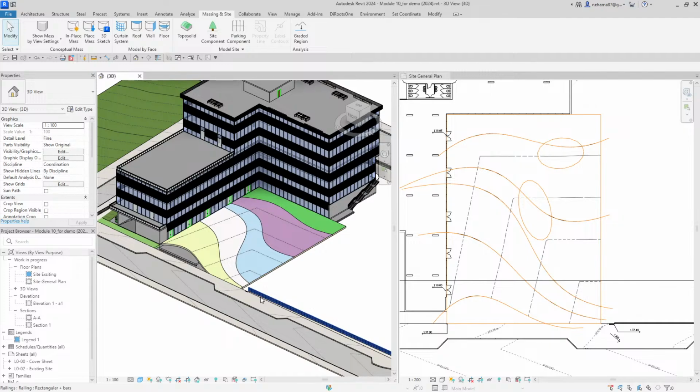So if the elevation points on a Toposolid are at 0, for example, and then you change the attached level to 3, it's not supposed to influence what I would call the absolute elevation. In order to change the absolute elevation, you would have to change the points. And this was done for convenience because it just makes sense that if you want to change the elevation, you would change the points. So that's, again, maybe something that we can discuss in further sessions.